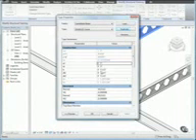Now let's modify the beam opening. We'll modify the beam by changing the size of the opening to allow for larger utility cables or similar services. The values for the dimensions are listed in the Type Properties dialog and are displayed in the beam diagram. Under Construction, for E1 or T length, type 8 inches.